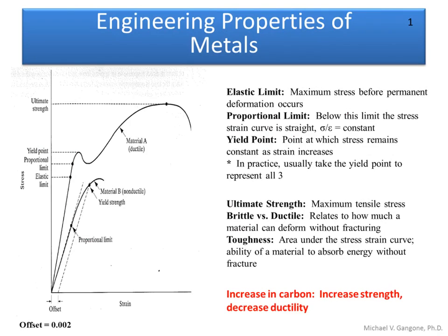Okay. And toughness is just defined as the area underneath the stress strain curve. So the greater the area under the curve, the more the toughness is. And again, these are easy things to ask on an FE question. Two stress strain curves: which material is tougher? Which material is brittle versus ductile? So on. All easy things to keep in mind, or to ask, I should say.